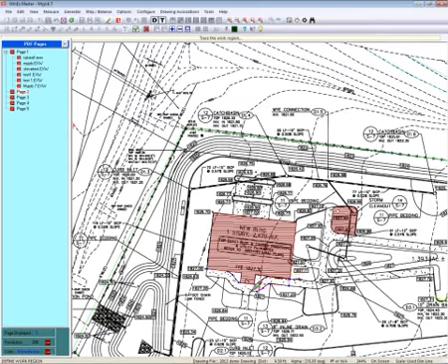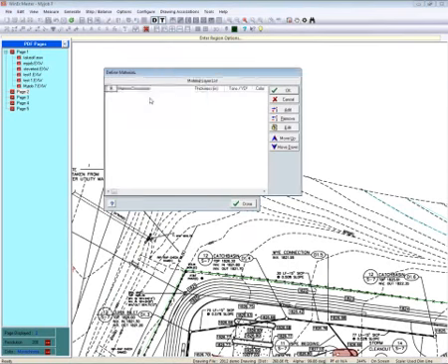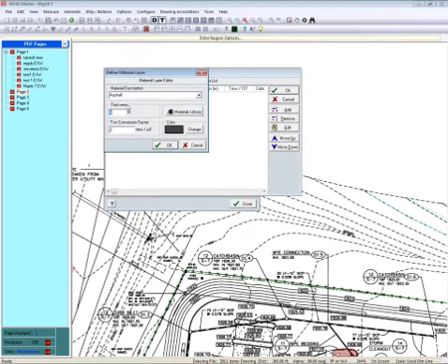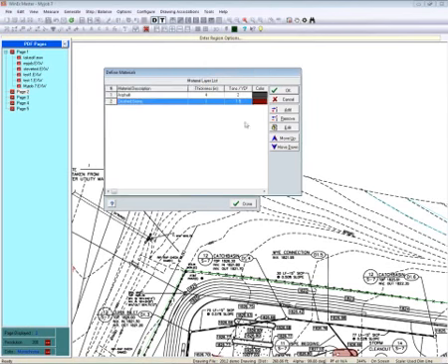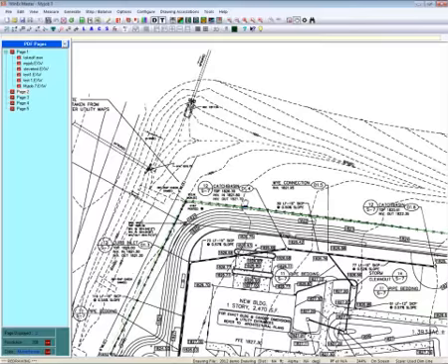So I'm just tracing this in. Again, you could use line tracker on this. You could hold your left mouse button down and trace along. And what I'll do is I'm going to finish this off now by going up to the Finish button. Click on Finish. Now it wants to know what subgrades that walkway is going to have. So maybe we're going to put in a little bit of asphalt. I'll leave it at 4 inches, and maybe we're going to put some crushed stone in there. Say OK. And we'll say OK. And I'll say Done. And if I come back down, there's my walkway.